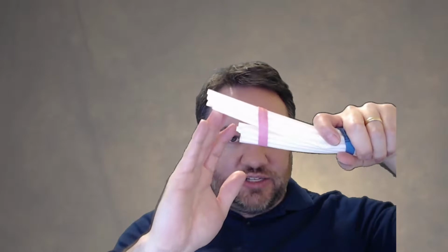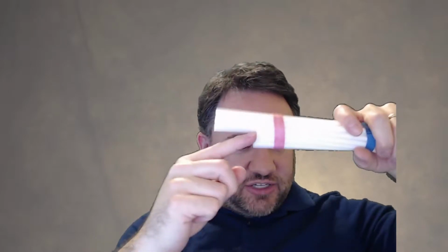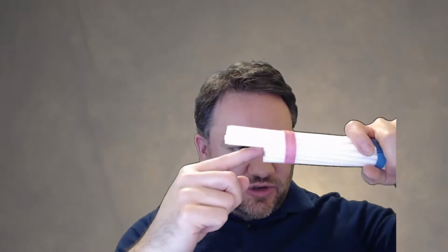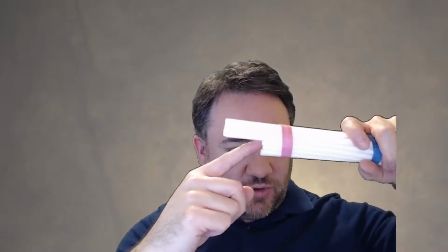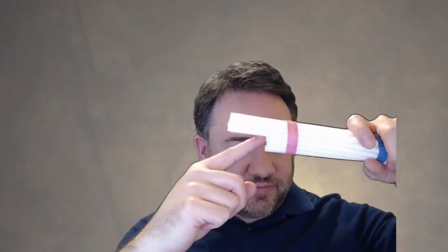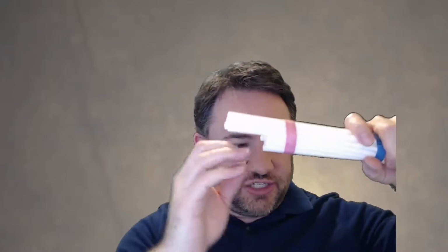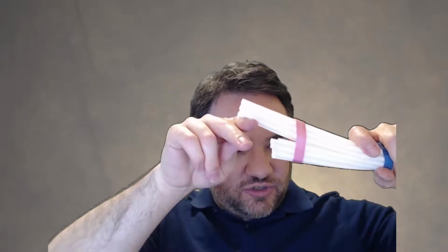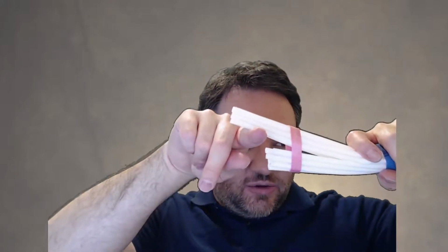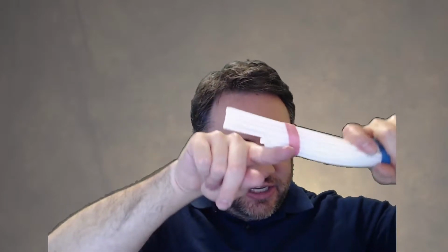Okay, and so I am basically having a stress concentration at this. This is what's called the re-entrant corner. It's the corner where the notch comes down. And at that re-entrant corner, I get a stress concentration, and that stress concentration could form a crack, especially if I have a bad notch geometry. And we're going to talk about what's good notch geometry and what's bad notch geometry. And so I need a way to calculate this condition. This is obviously much worse than if I load here, because here I'm engaging the entire cross section. Here I could get a crack, and that crack can propagate through the entire member.